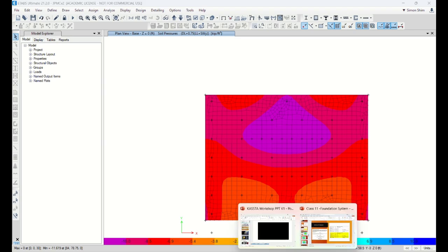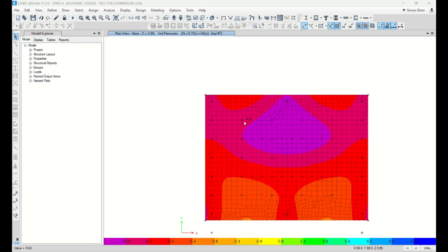The second one is, since I think you are aware of the spread footing design, what we do is size the footing based upon the service gravity load divided by allowable soil bearing capacity, which means you're sizing the footing dimensions.